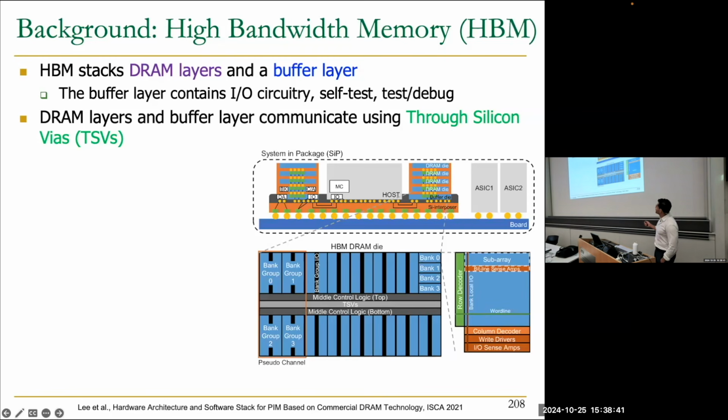So this is the SoC, the system in package, and here we have the HBM chips. These circle things are the TSV connections, and this is the substrate, and the connection between the host and the DRAM chip is done with something called micro bumps. That is this thing here that connects the host and the die in the silicon interposer. So this is a little bit different from the DIMM form factor, because you cannot plug and unplug. You put the die, you put the device in the package, and once it's there, you cannot remove it.